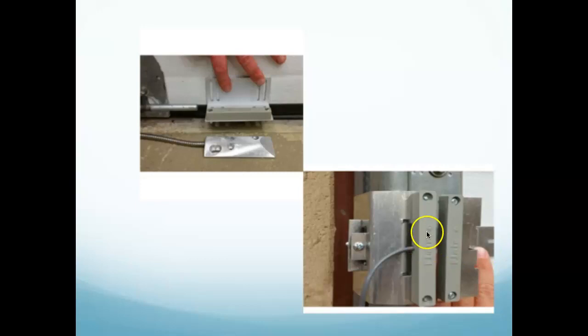Now you've got your sensitive contacts in a plastic housing here, right? There's metal on the frame, but there's plastic housing here. They're going to get banged up all the time. If I were you, I would stick with floor mounts. Let your situation be your guide. When you get out into the real world, you may end up liking these for one reason or another. Your particular application may be better, but I would strongly suggest you use these. I've never seen one of these fail from damage my entire career. They're just built so darn well.